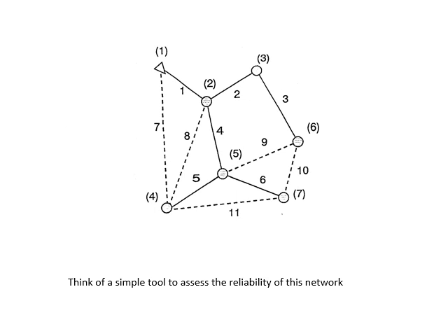This is an example showing that the source is 1, and the tree network that takes water to nodes 2, 3, 4, 5, 6, and 7 is shown as continuous lines, and the redundant links are shown as dotted lines. When we increase the dotted lines, we increase the reliability. By doing that, if you can count with me, the basic closed loops will be 1, 2, 3, 4, and 5 closed loops, which is the same as the number of redundant links, as we will see in the topology section.